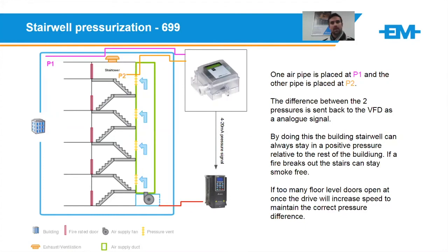Got a question from Trevor regarding ultrasonic sensors. Ah, the foam question. Yes, I love it. It probably will pick up foam. I have seen different solutions for foamy water. Often they would have a pipe running down into the actual fluid, so that the foam will be building up around the pipe.